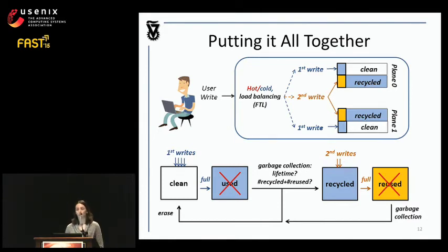So there's two things to notice here. First, at any point in time, and this would probably depend on the workload or maybe on various performance constraints that we have, we can abort second writes. The SSD will continue to operate just as a normal SSD, and of course the performance will be exactly the same. But the more we're able to have the blocks cycle through all of these stages, the utilization of the SSD in terms of the number of writes we can perform increases.